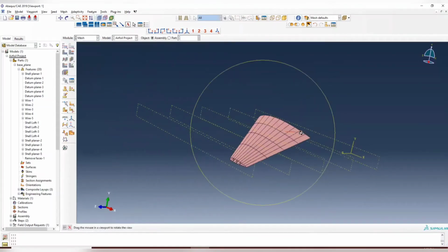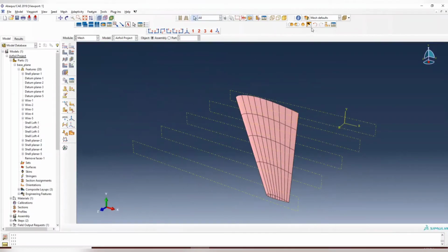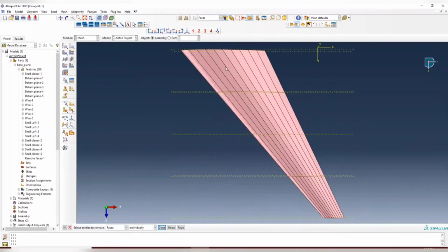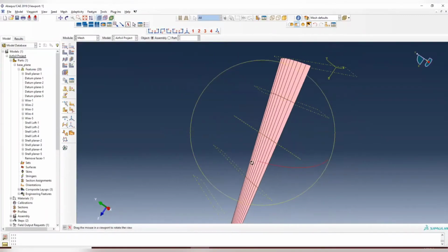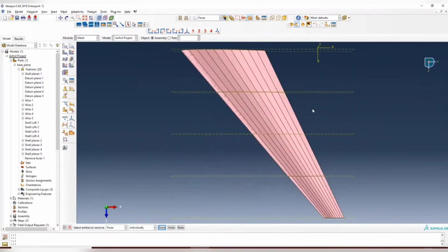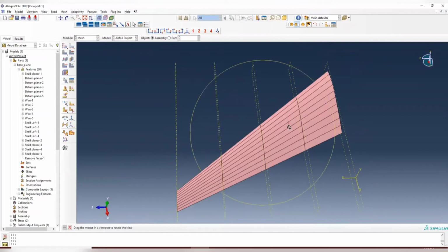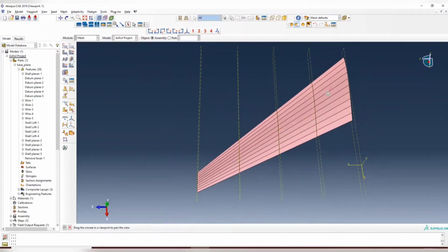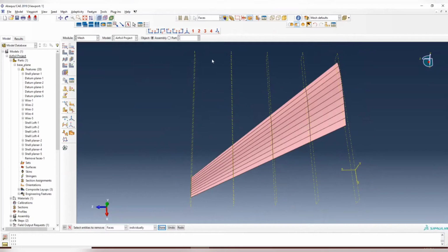Now we go to the mesh part. The mesh part is one of the difficult challenges we have. So choose the XZ plane, or this direction probably. Move it to the side direction. We are going to have the same number of nodes for different sections. But notice that the length is different, so we cannot directly apply a global length and do it.